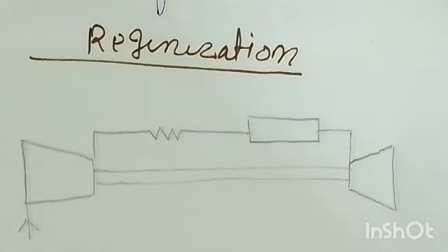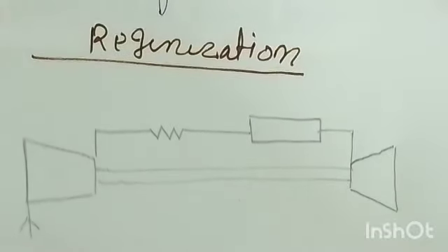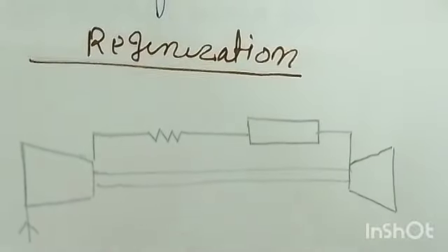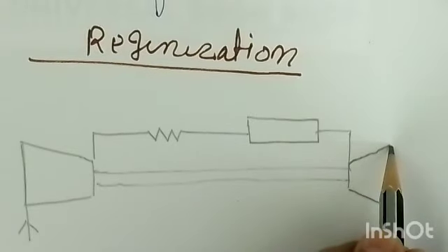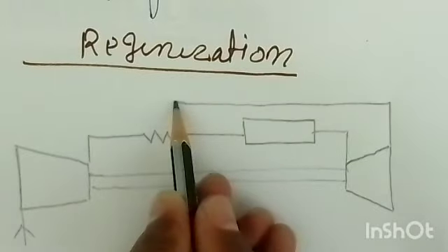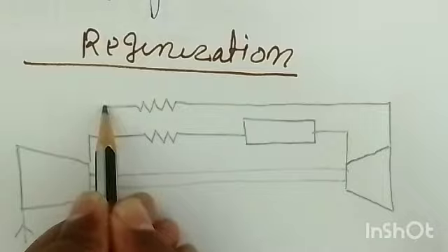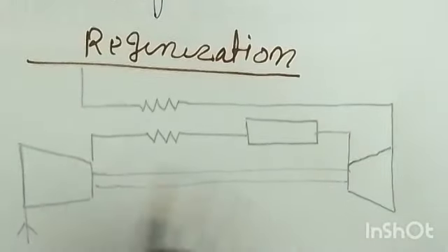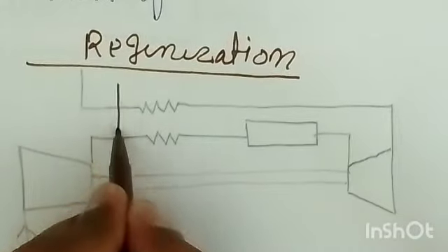But as we are doing regeneration, we don't leave the gases into the open atmosphere, nor do we send them directly to the compressor. So we will reutilize that. For reutilization, let's say this is the exit point of the exhaust gases. So these exhaust gases will come here, and here we will provide one heat exchanger. Here we will provide the heat exchanger, and this is the exit of the gases. So this will be coupled.